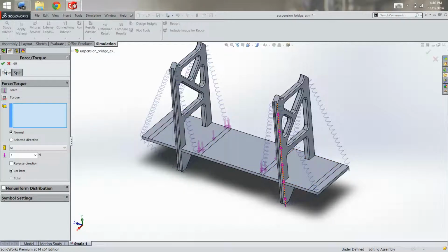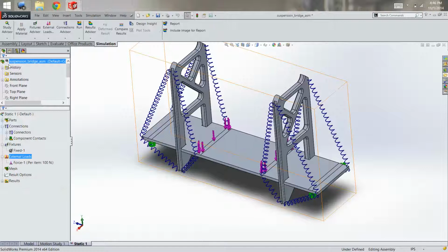So if you had trouble with problem 1 on assignment 7, try doing that: redefining the load and fixture areas as thin rectangular faces using split lines, rather than just an infinitesimally small line, and see if that will fix your simulation.